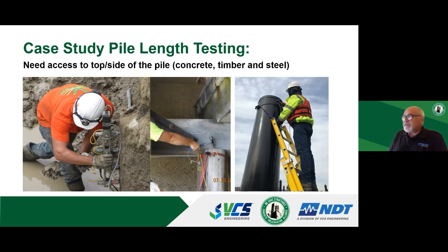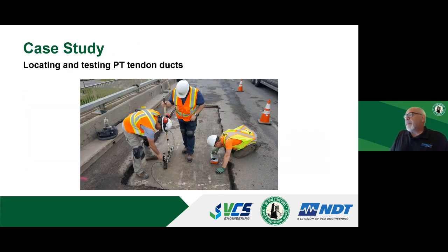Again, pile length testing, we've got a concrete pile, it has to be exposed, so we're doing some excavation or shoring as needed to get it to the piles. Sometimes it's below pile cap and the shoring is very complex. Timber piles in the middle, we use the ratchet strap with our sensors, and steel piles on the right happens to be a marine. Question was, at what point does the pile change to a concrete filled pile? And we could determine that as well.